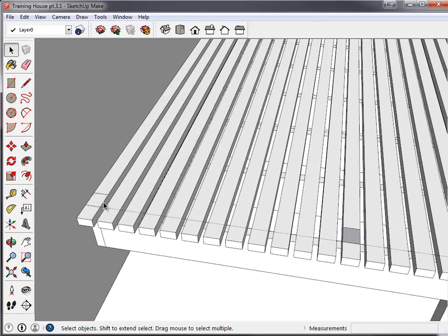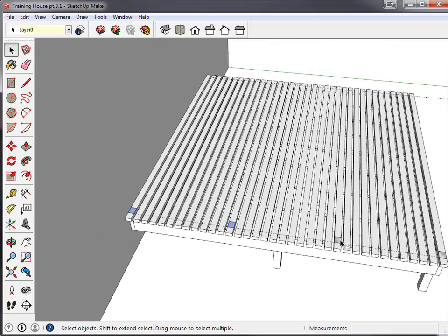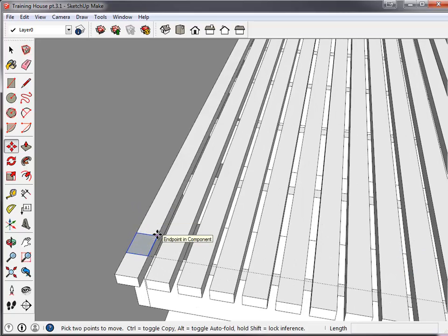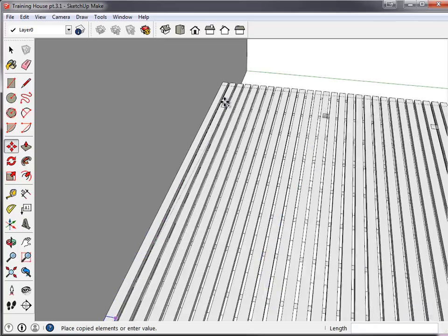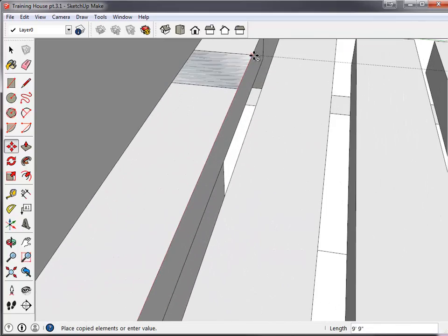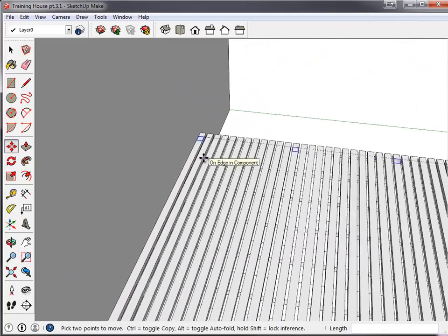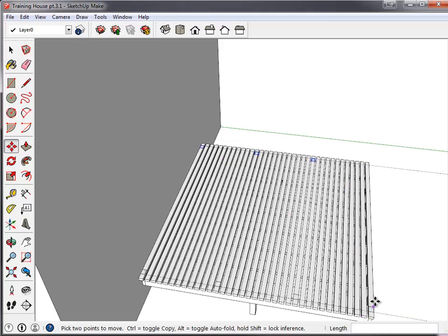Alright, so to save some time, we're going to press the Shift key and select the first 3 measurements for these lines. Once again, I'm going to grab the front right edge of my back support, press Control, and copy myself a set all the way across my drawing. You'll notice I did not do the front one because the front is slightly different.